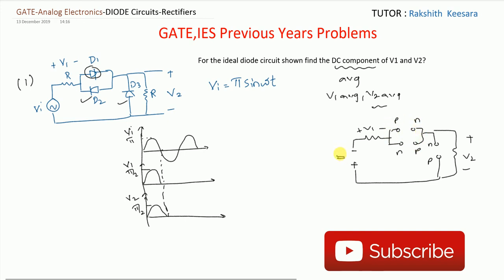So if I draw the equivalent circuit, it will be like this. Since this diode is short circuited, our output voltage V2 will be 0. So the entire voltage will appear across V1. This is minus plus, but here V1 is stating the negative of the voltage, so it will again become positive. So this will be like this now. This magnitude is pi because the total voltage appears. In the positive half cycle only half voltage appeared and V2 is 0. So this is our waveform now.